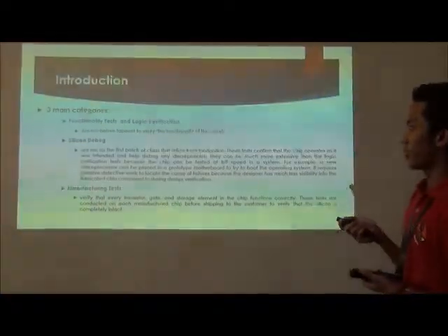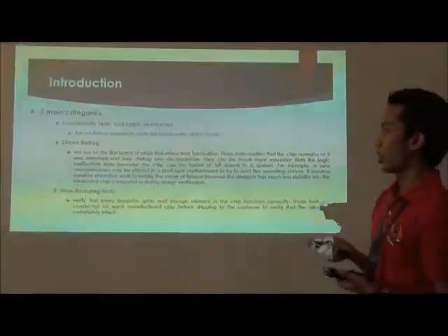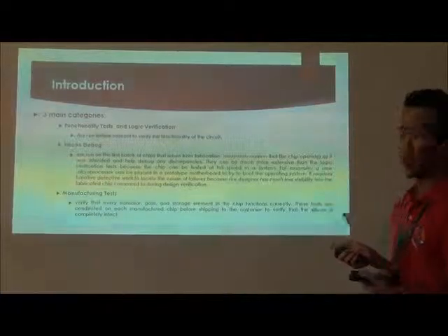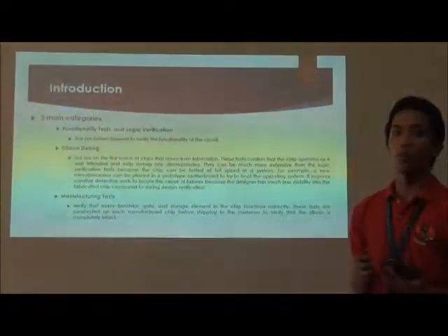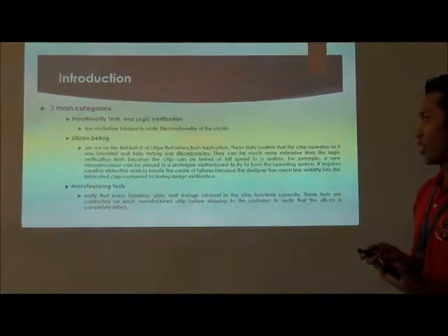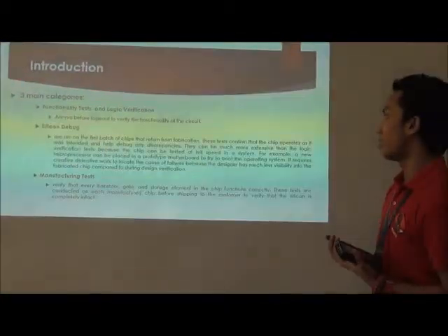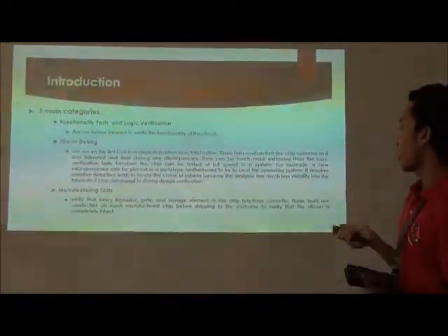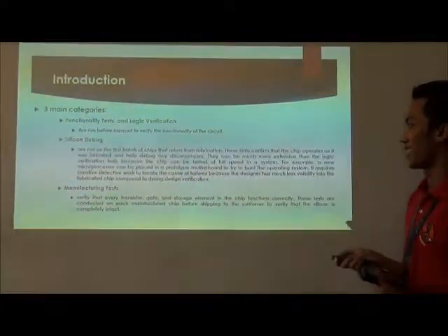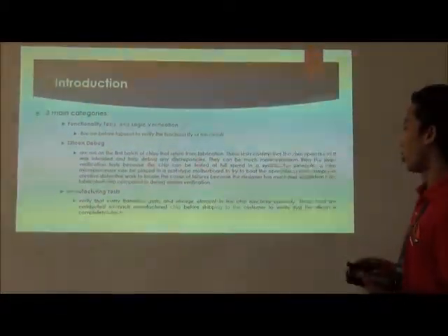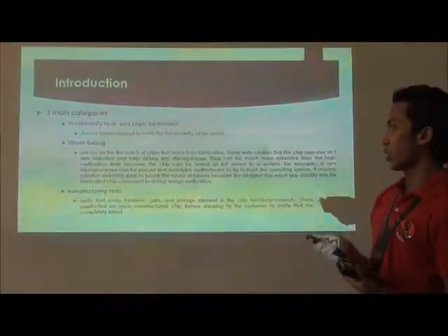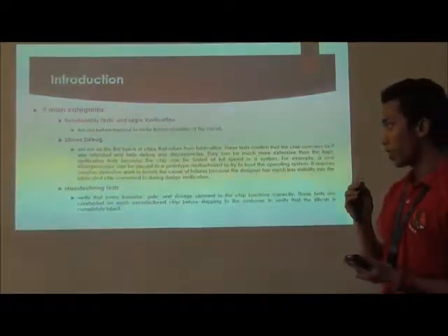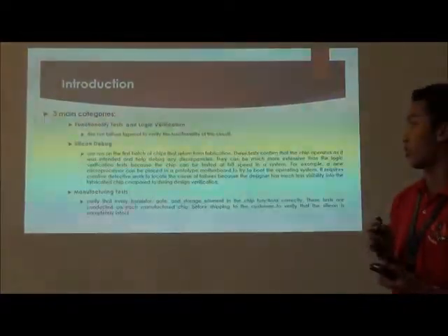In the functionality test and logic verification, we have to run tests before the chip comes out to verify the functionality of the circuit. The silicon debug is run on the first batch of chips back from fabrication. These tests confirm that the chip operates as it was intended. They can be much more extensive than the logic verification test because the chip can be tested at full speed in the system. For example, a new microprocessor can be placed in a prototype motherboard to try to boot the operating system. It requires creative work to locate the problem because the designer has much less visibility into the fabricated chip compared to during design verification.